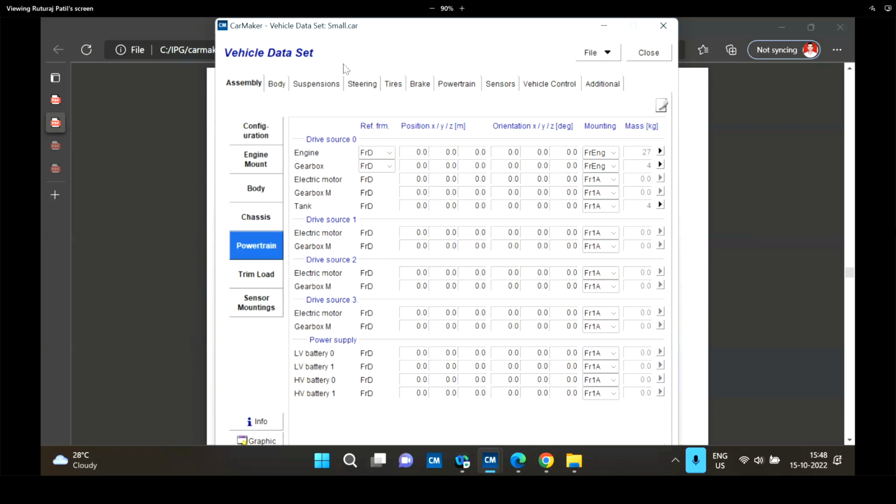As the preliminary round of phase one has finished, I'm expecting most of the teams will have such models. In the initial modeling phase, input those values accurately in IPG CarMaker, ensuring that the reference frames are taken into consideration. If you make even a slight mistake in understanding the reference frames, the model won't be accurate.